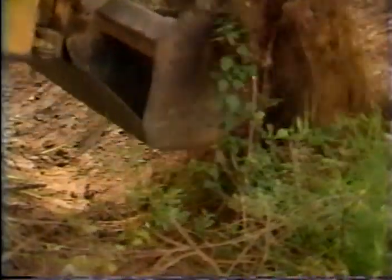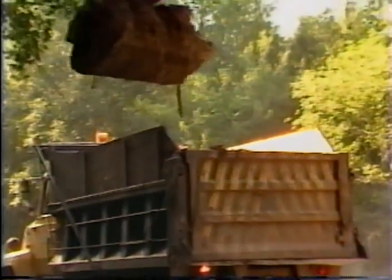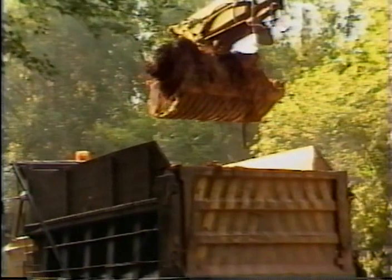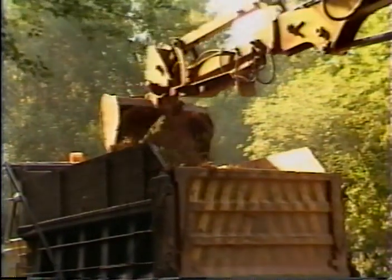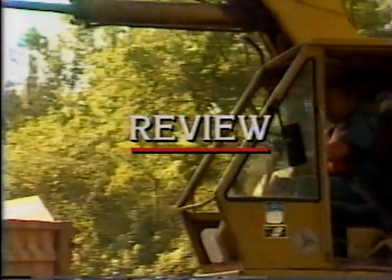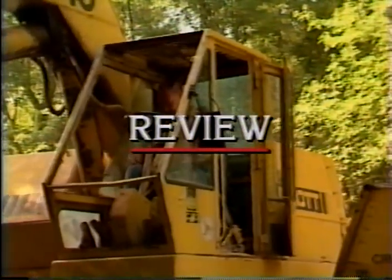This arrangement minimizes the time trucks spend waiting to be loaded, as well as wait time for the excavator. The proper number of trucks makes the ditch maintenance operation more efficient. Let us review briefly the steps required for ditch maintenance with a hydraulic excavator.